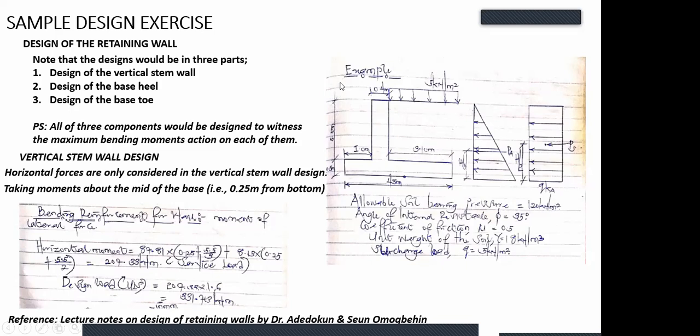Instead of us using 6/3 straight, look at this very interesting situation here. We are taking horizontal moment. The first horizontal moment is due to my earth material. This is 87.81 times, and we know it's triangular in nature. It's going to act at H/3 from the base of where you are considering. But you are going to commit a great error if you use 6/3.